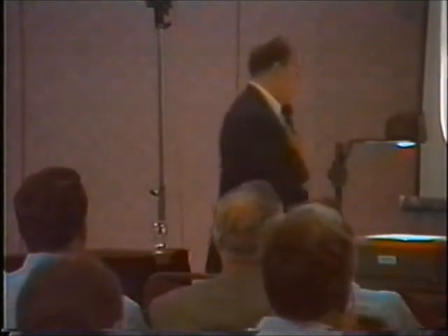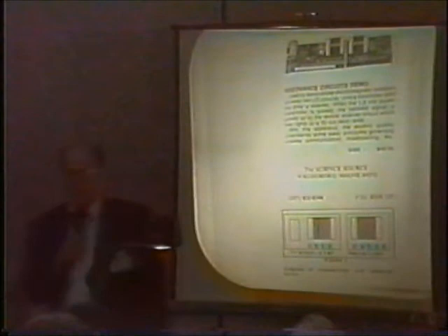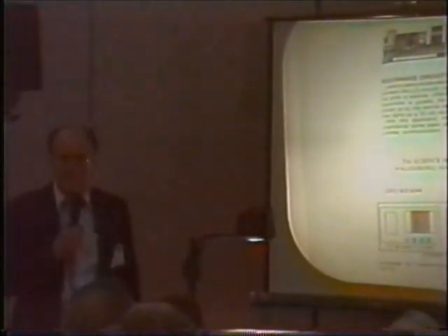Well, there has to be some sort of circuit interrupter, a key or something else that goes with it. Well, there's a capacitor in there. It's a small capacitor. Actually, you can see there's a butterfly capacitor there that's in the, like 250 microfarads or something like that. Or picofarads, it's probably 250 picofarads, which would get you into the AM radio frequency with that particular coil winding. Right, a little tank circuit.